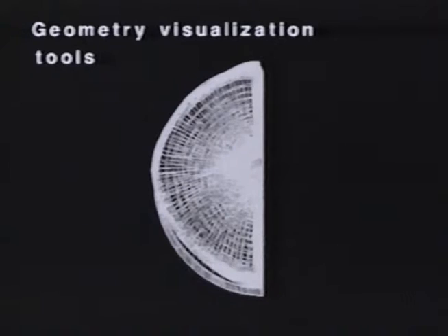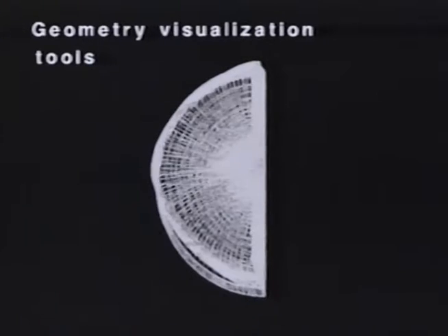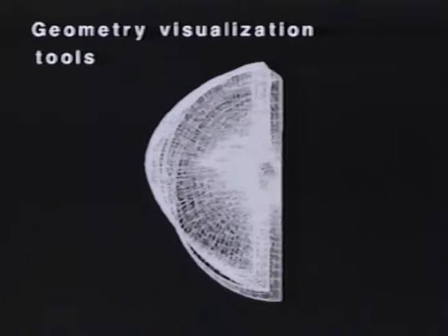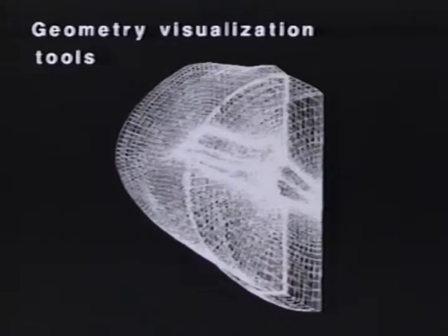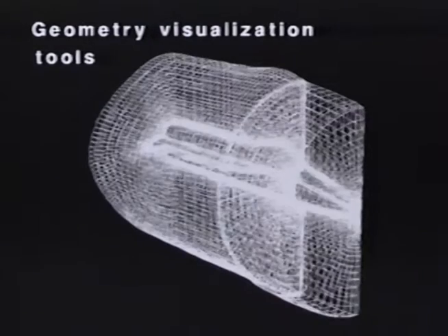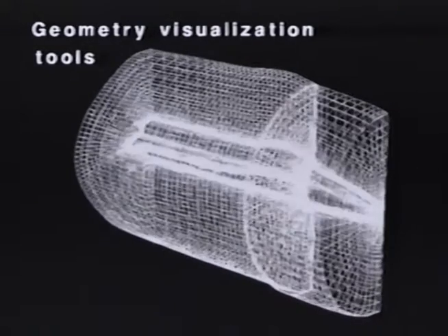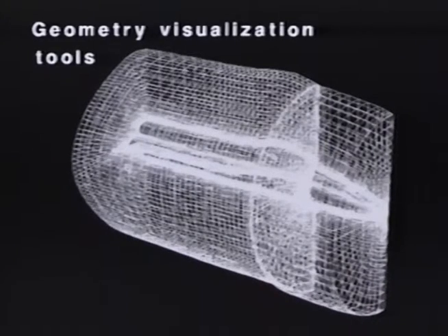For discussion of the next group of visualization tools and techniques, we'll switch to a different and more demanding dataset. Here our node and element count has increased by a factor of 10, and we've gone from a single block to a multi-block environment. First, the Mesh Boundary tool has been used as before to display the computational grid itself. At the interior edge of that grid is the bounding surface of interest in this analysis.